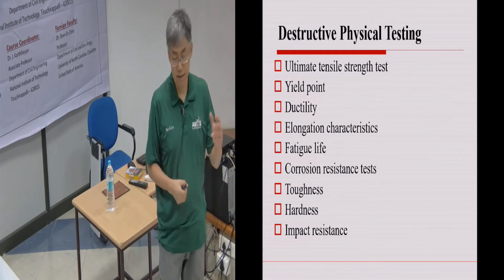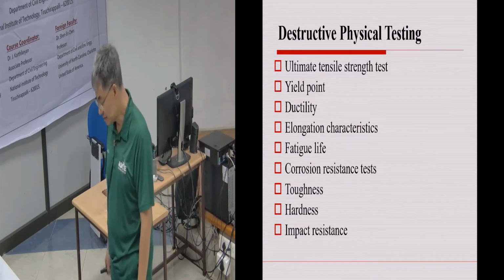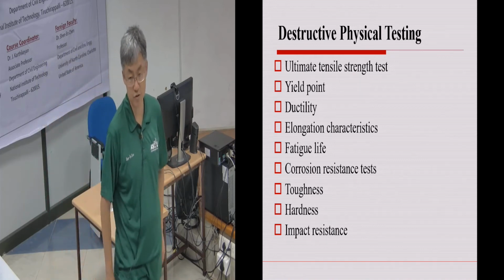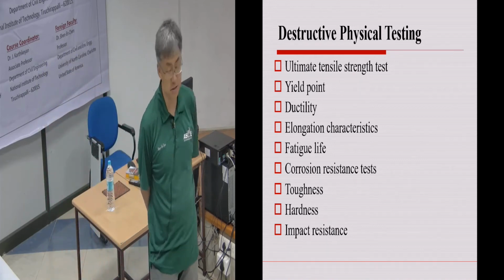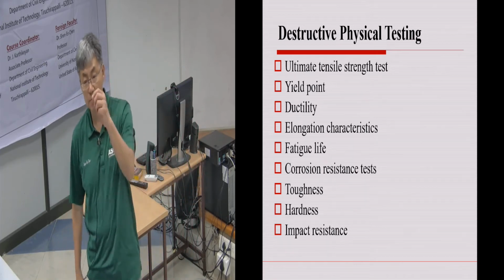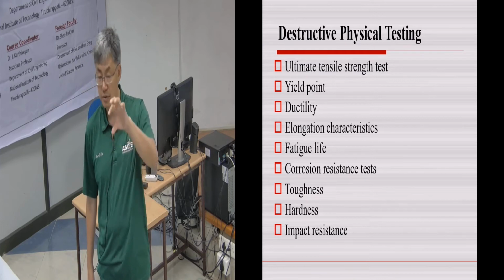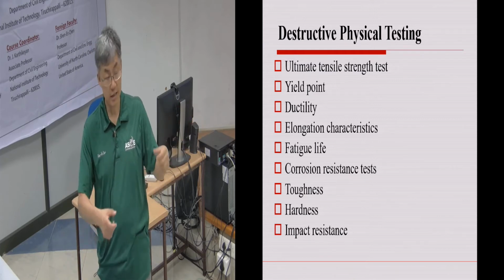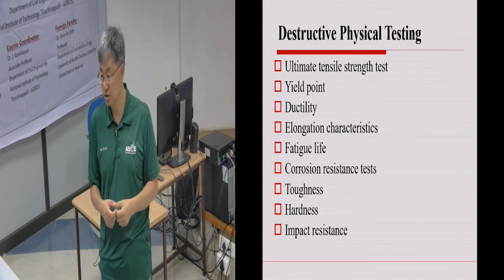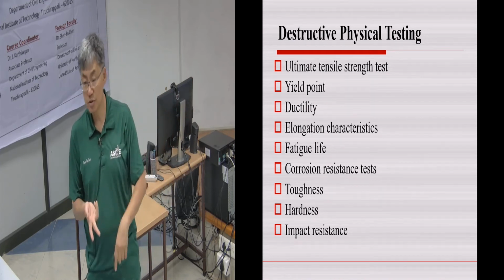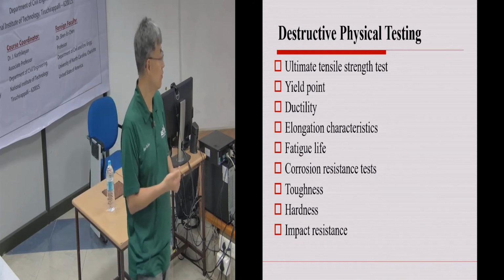And then let's talk about some other testing methods that may be required of a civil engineer, okay? So there is always some kind of destructive testing method. You may be getting a part of the materials, maybe do a coring, and then bring the concrete back to the lab, or a steel beam, and then you can do destructive testing to determine the various parameters: yield point, ultimate strength, and so forth, okay?